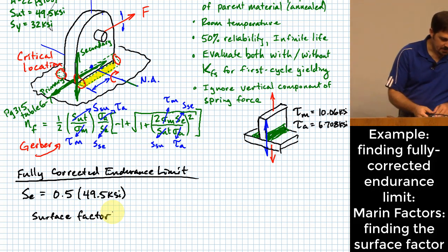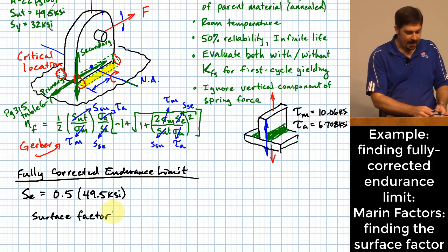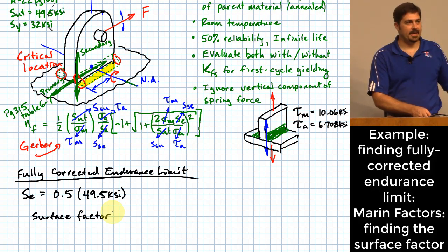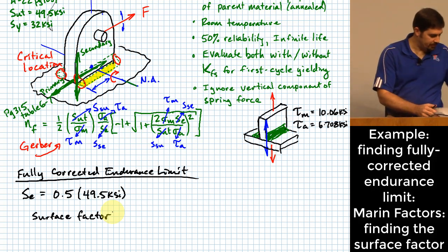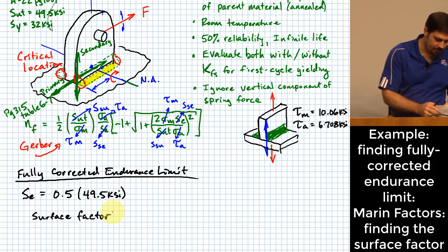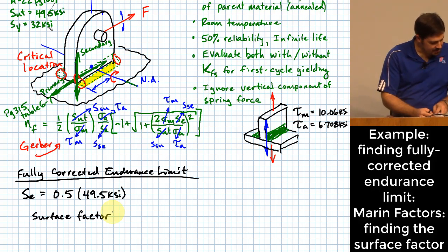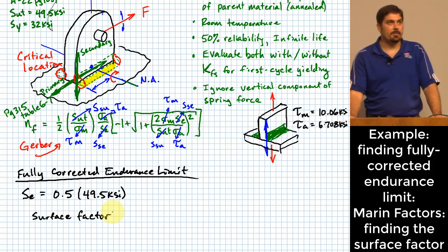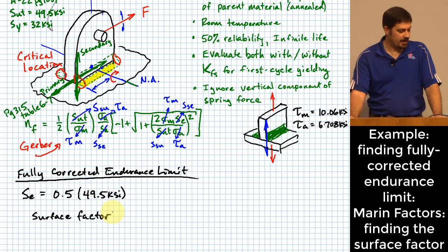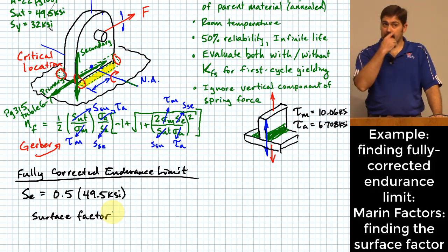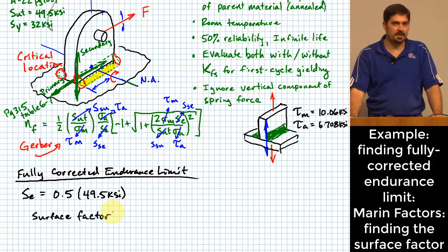Okay. My best advice as far as a surface factor is welds are about one of the worst type of surface that you can have for fatigue. Okay, so even like when we flip back here to chapter 6, where it kind of tells you how you might go about finding some surface factors. Here we go, page 296. Okay, we probably want to pick about the worst possible thing in there, which actually kind of makes some good sense. The as forged description that's in there is going to be the thing that gives you the highest amount. Well, it's really going to be the lowest Marin factor, right? But it's the highest amount of compensation basically for a bad surface, right? So we're going to put in a factor of 39.9.